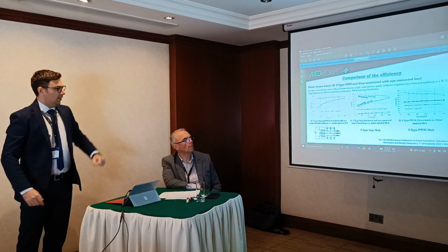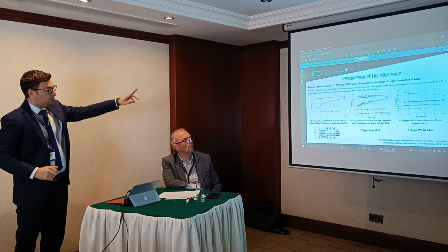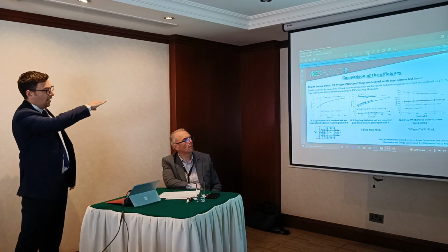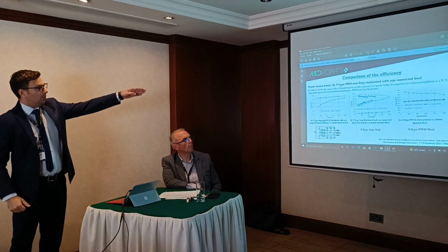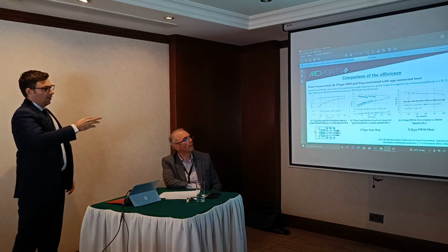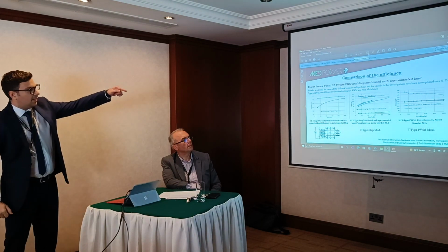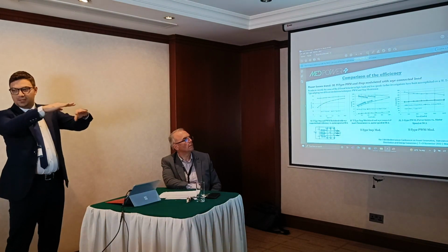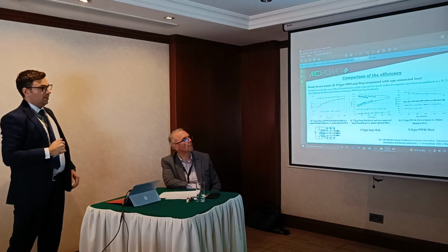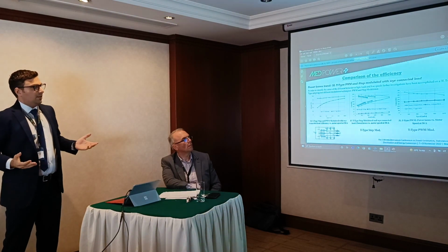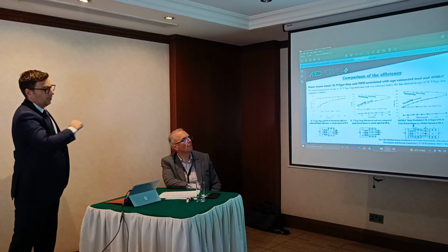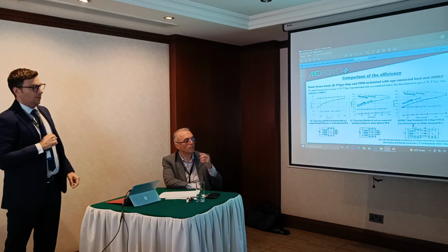If we consider 3-level in wye connection, and in two cases, step modulation and the PWM modulation, we know that we have the same trend, a flatter one, when we consider step modulation, because if we consider in the middle the separate power losses, we know that while the conduction losses increase, the diode losses decrease. This means that the efficiency remains about constant, flatter. And on the right, we can see instead the case of PWM, and the behavior is different from the middle. The same occurs in the 3-level T-type on the right, in case of asymmetric hybrid multilevel converter.